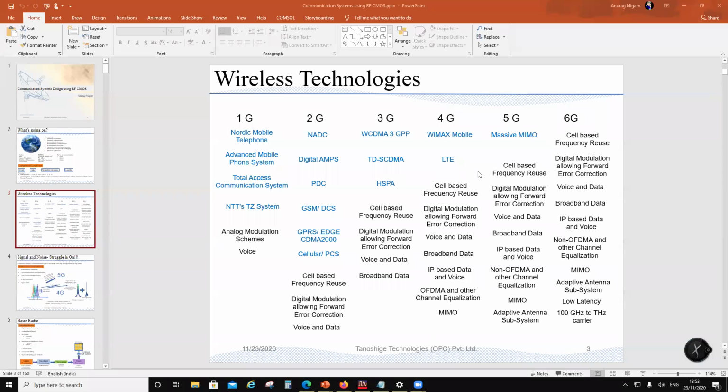Now, between transmitter and receiver, there is an agreement that we are going to generate the same PN sequence. So if we generate the same PN sequence, when we demodulate, we get each other's information. But all other people who are allotted different PN sequences would not see our signal at all, because it is going to be just white noise, because the correlation function is 0. So that's what CDMA is.